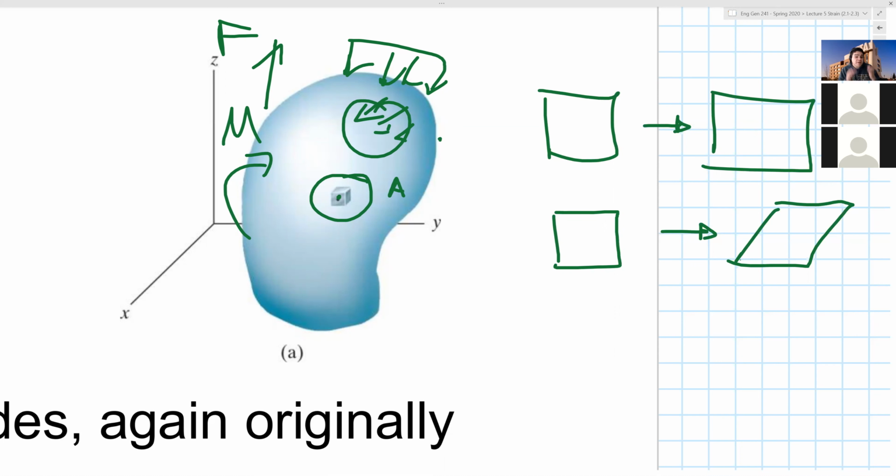Six faces, right? So now, couldn't it stretch also in the X? Couldn't it stretch in the Y? And couldn't it stretch in the Z? Those stretches in those normal directions, aren't they called normal strains? But couldn't you also change your angle with respect to the XY axis? Couldn't you also do the YZ axis? Couldn't you change your angle in the, what else is there, XZ axis? So you can have 3 normal strains and you can also have 3 shear strains. Does that make sense? Just before we started showing you the picture.